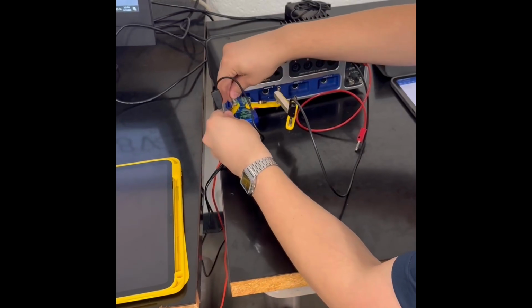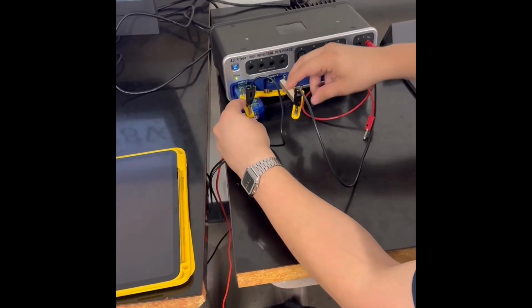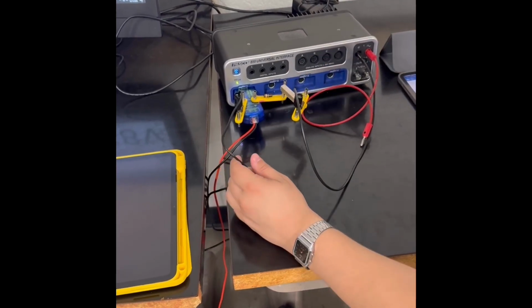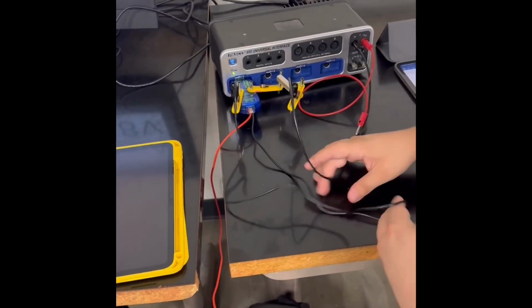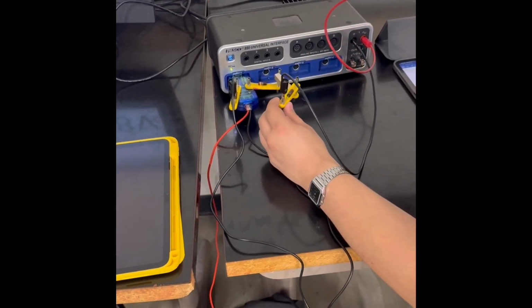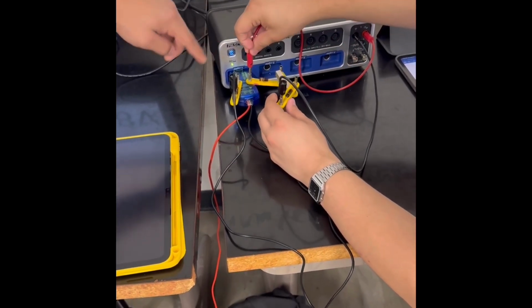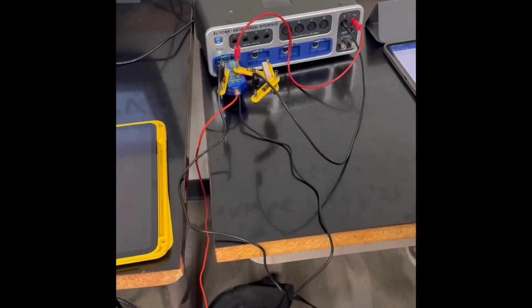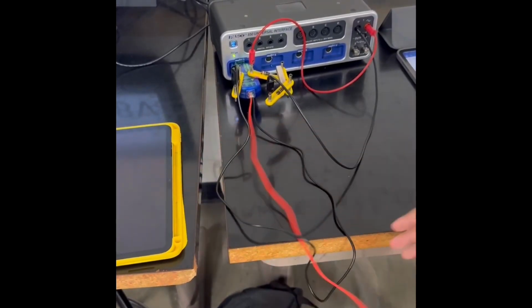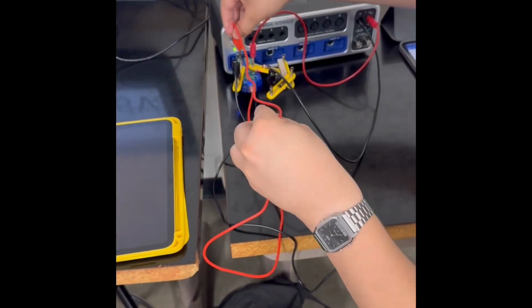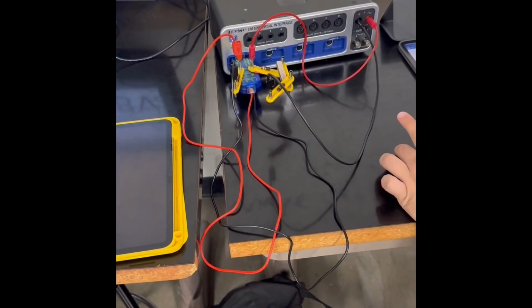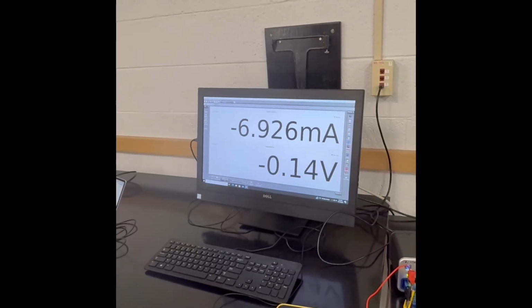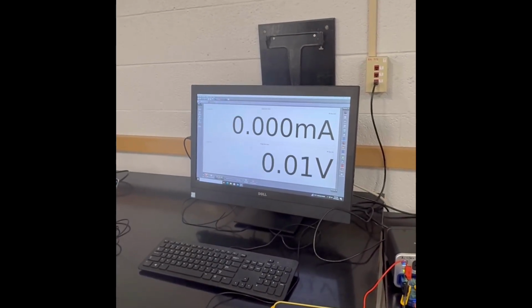In the video shown, you can see how we're going to go through the next resistor, as we're trying to figure out if it's the correct way to display it, and if our source would make sense once we have it plugged in. For resistor 4, we got 6.39, I believe, volts, and our current will be 17 milliamps, about there. And then what we have for our component, which is the source, would be 7 volts, and the current would be negative 1.1 milliamps.